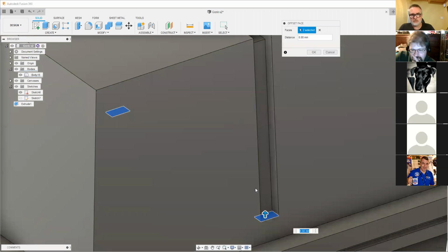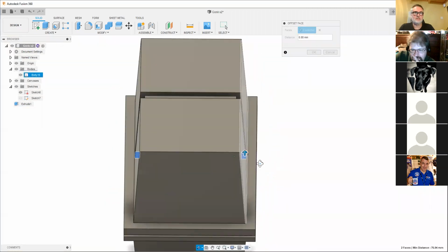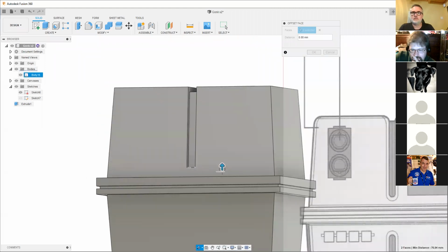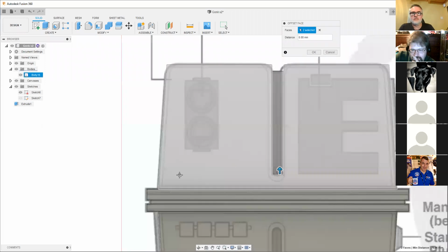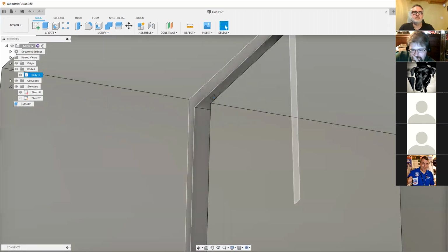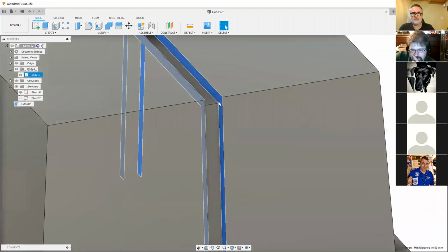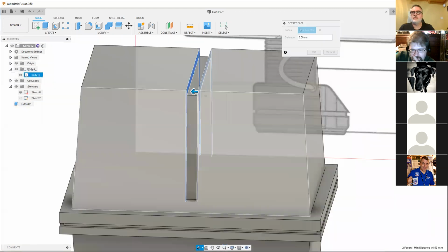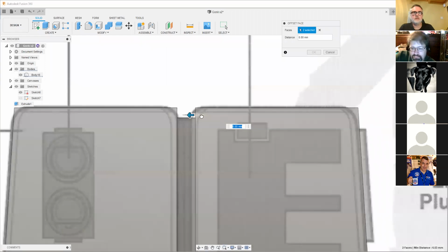The thing to remember is that if you're going to adjust something where you want it to be symmetrical, make sure that you select both sides. So if I wanted to just drag that down a little bit further, I think actually I'll pull it down to about there. I can do. And likewise, if I think that this gap needs to be wider, I can press the Shift key and select both of those, press pull, and I can make that gap a little bit wider as well, or narrow. So you can adjust things as you go through once you put it in there.